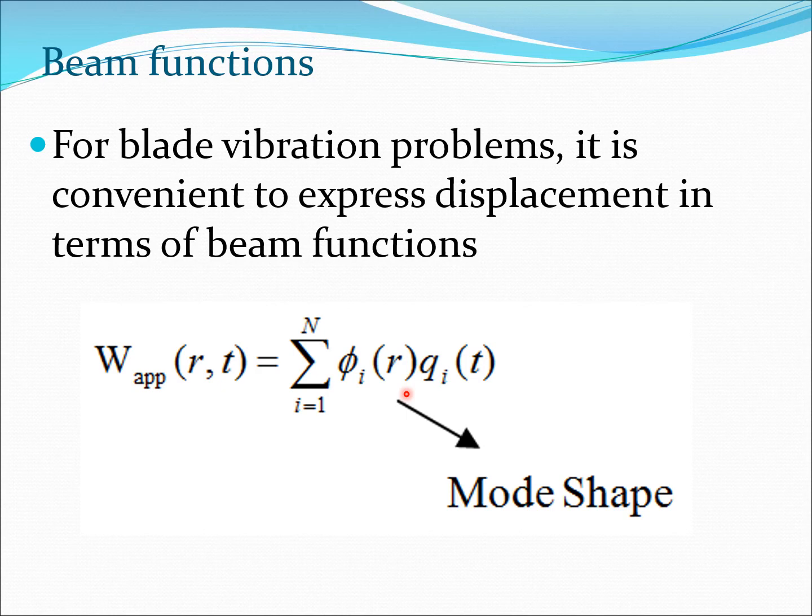So if you have a non-uniform beam, or a non-uniform rotating beam, or a uniform rotating beam, you can always use the basis functions or the mode shapes coming out of the uniform non-rotating beam, which we have derived before. So that is why beam functions are very important.